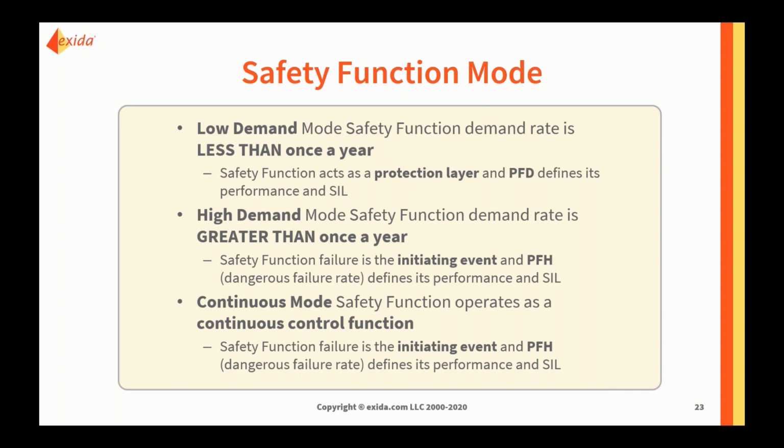The way in which that safety function sits in our analysis is completely different. Here, we find that each individual failure of our safety function is much more likely to escalate in harm than it is to be caught and fixed by a proof test. So the PFD average, or PFD, really doesn't work well in this application.